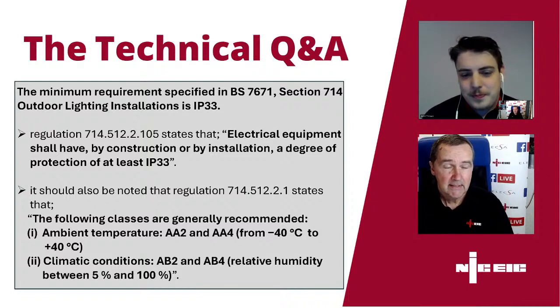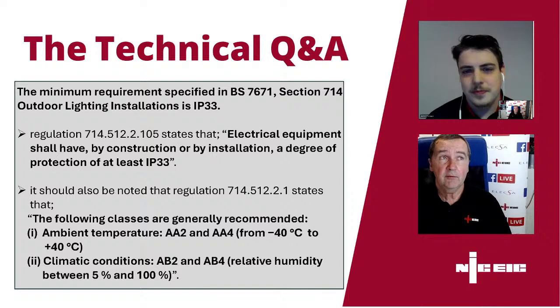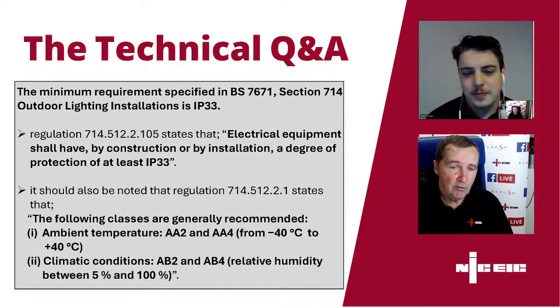Sometimes people get concerned that if they've only worked on part of the installation, the date they're recording for the next inspection covers the whole of the installation, and it doesn't. It only covers the work covered by that certificate.